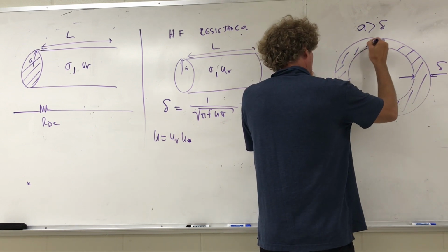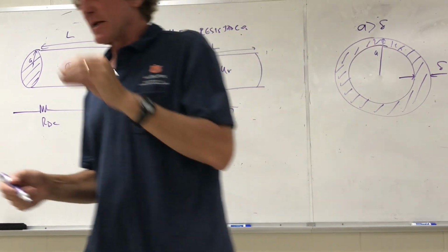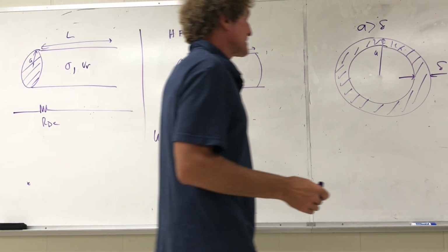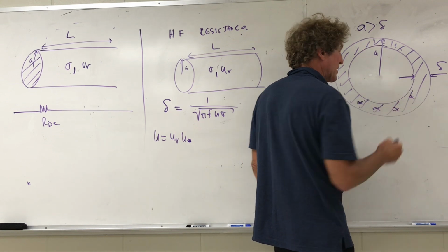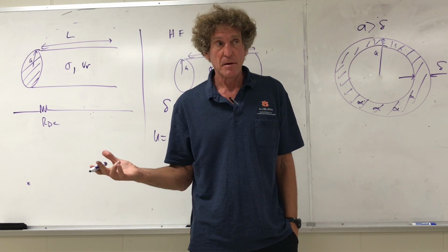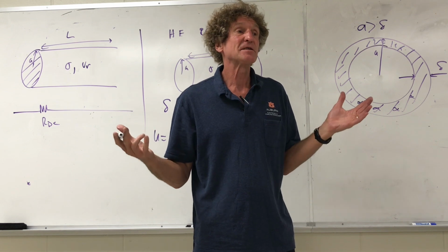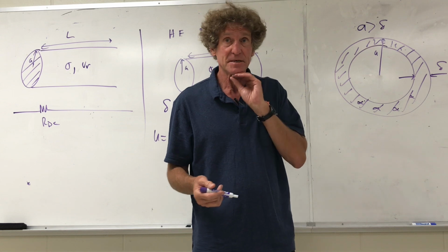If you actually do a formal integral of the value of the current density versus the area of that wire, and you include the skin depth effect, which is really 1 over alpha, you get exactly the same result. So if that's the case, all the current flows through this purple area. It flows on the surface of the wire. How could you have skin depth greater than A? Sure, DC. If the skin depth is greater than A, just assume it's DC. That's the easiest calculation.